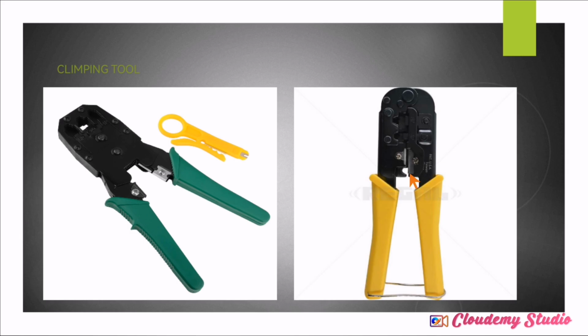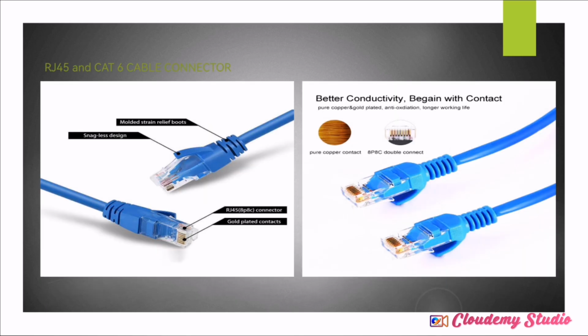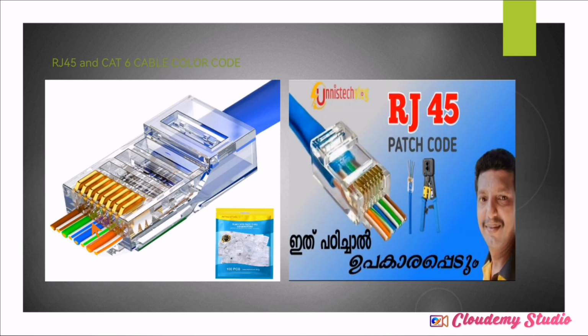Then you don't twist it hard, but you move it clockwise or anti-clockwise while holding it, not so hard, because you may end up cutting the cable. Moving it loosely, you'll be able to cut this part. This is just the cover of this cable. Then you remove it nicely and have the naked part like this one.